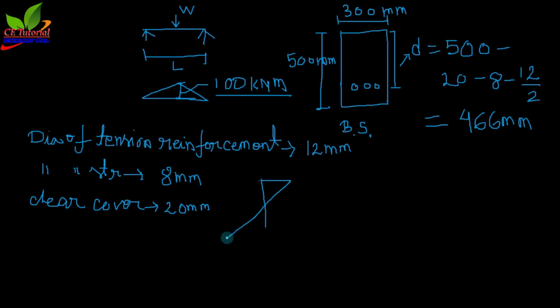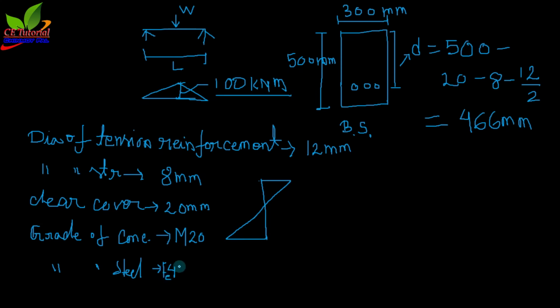Now from the stress diagram you know that we have to assume the grade of concrete also, or it may be given in your question. Suppose the grade of concrete is M20 and the grade of steel is Fe 415.